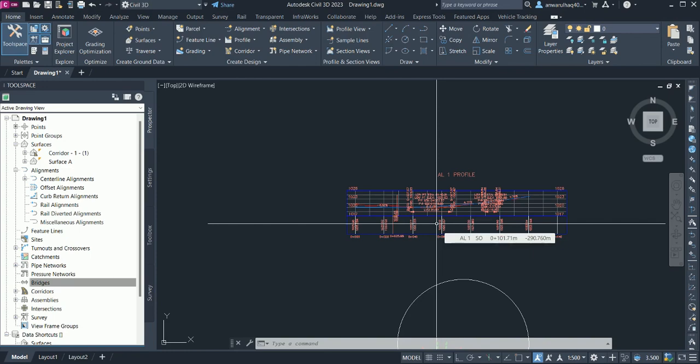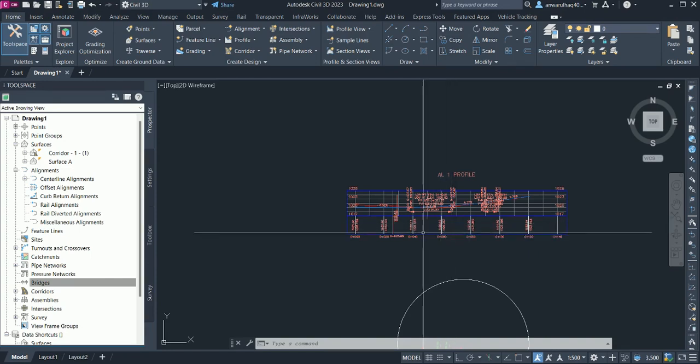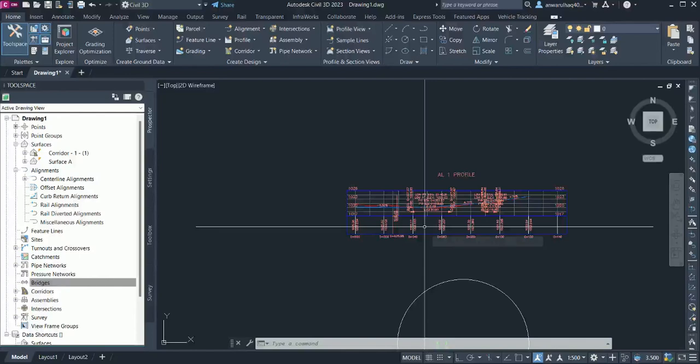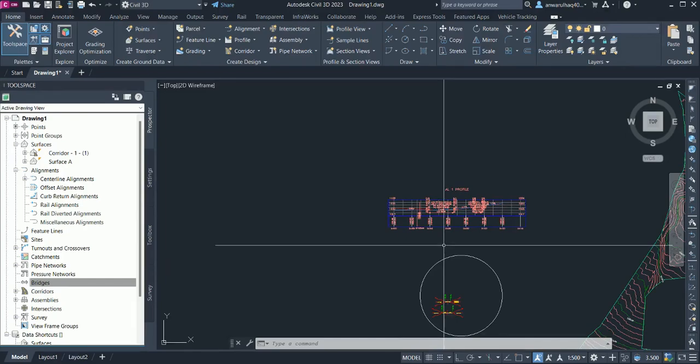Sometimes the grade is very high in canals, and you need to provide proper protection, because the critical velocity will be high and can erode your canals. So there are many consequences. You need to consider and address everything, and come out with a solution if a problem is there.